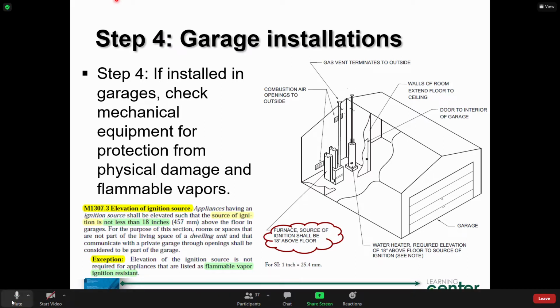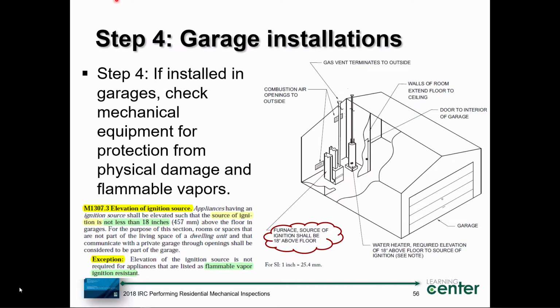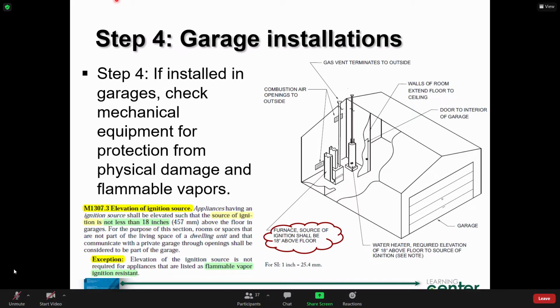We're looking at the appliance only. Just look at that furnace. Think about how a furnace works. I agree with you, like a spark igniter to ignite gas at the manifold. What else? A pilot flame? The pilot light, yeah, the little spark igniter. How about a glow coil? We don't have standing pilots anymore, but we used to.